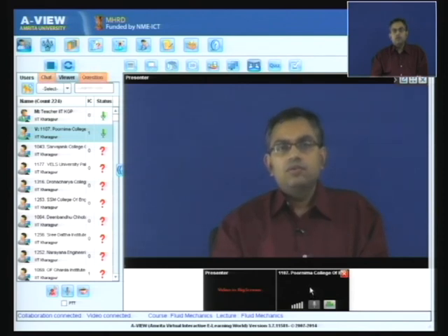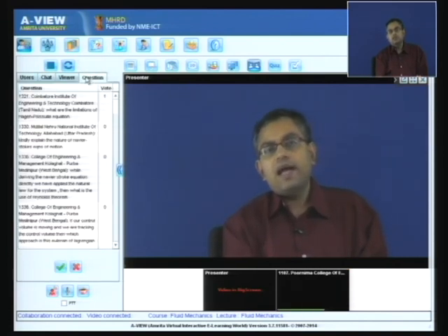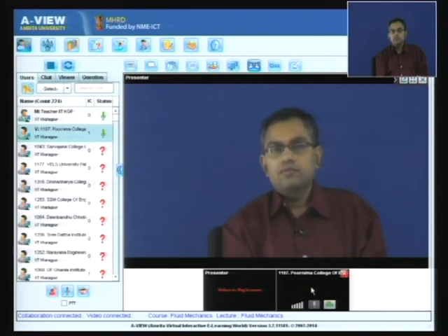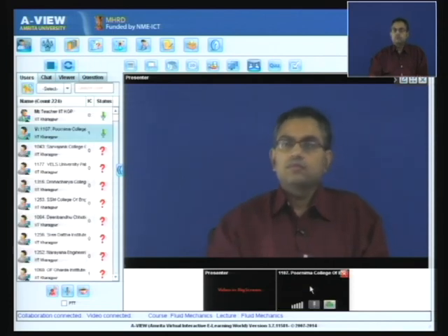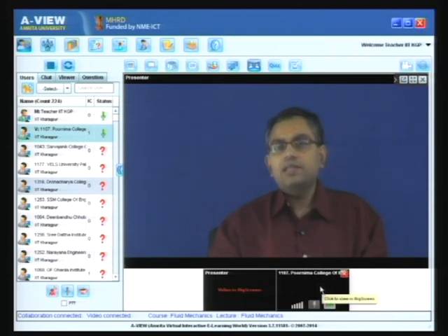Sir, I want to ask, is there any generally accepted theory for turbulent boundary layer thickness? Or laminar boundary layer thickness? All theories are accepted. Actually, for laminar boundary layer thickness, for 99% of free stream velocity, yes, we take the thickness. But in case of turbulent flow, what do we take? The same 99% of average free stream velocity instead of the 99% of u average, u infinity? Even average.